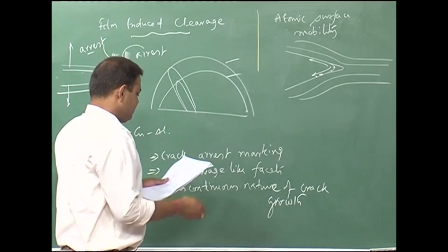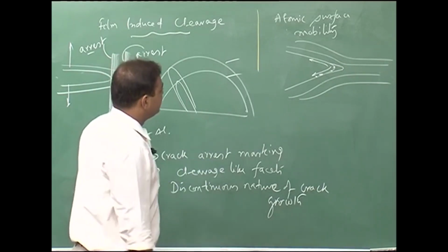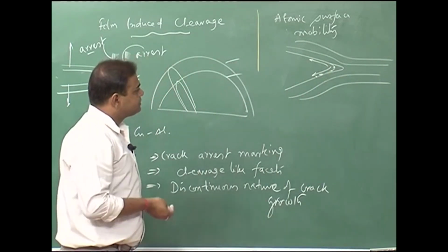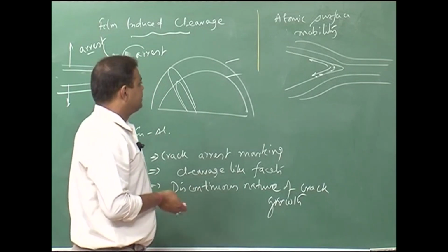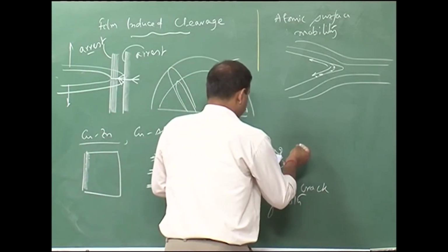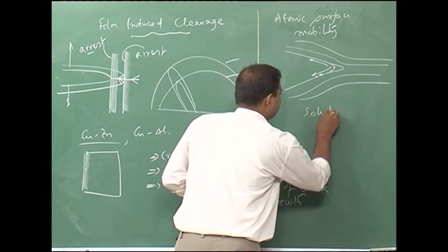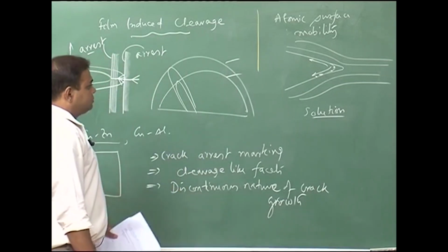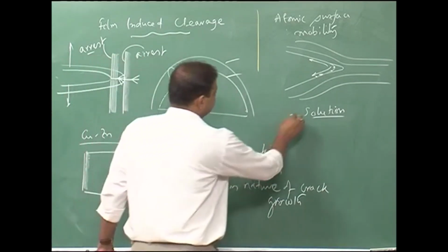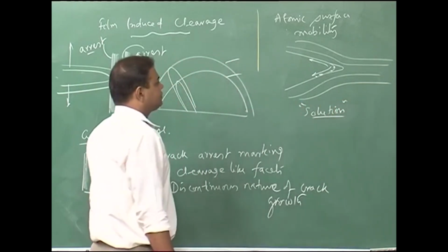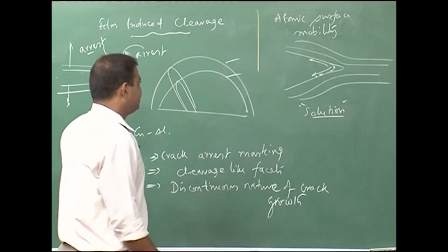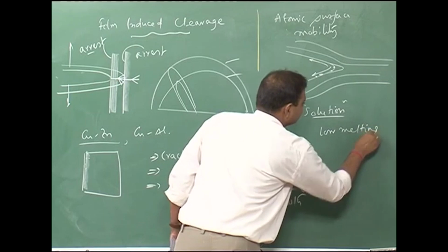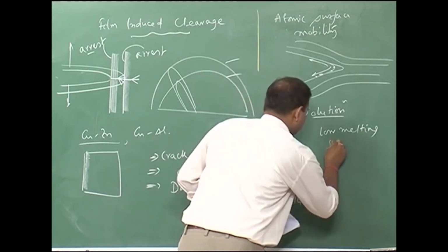and here the rate at which the surface self diffusion is happening will decide the crack growth rate, and here the effect of the corrosion phenomena or the environment solution is that it changes the diffusivity of those surface atoms, and it is sometimes associated with the low melting surface compounds.